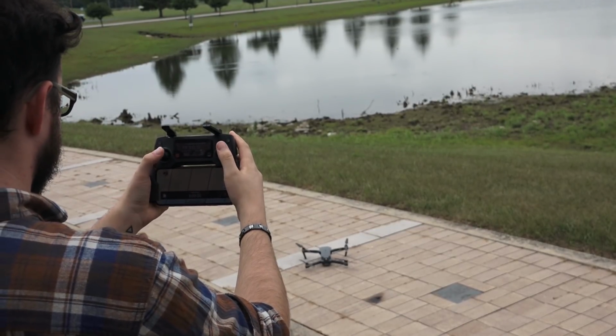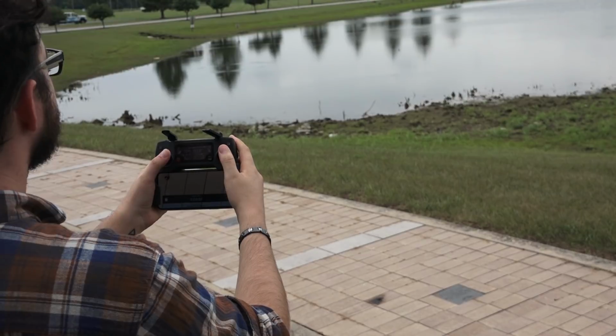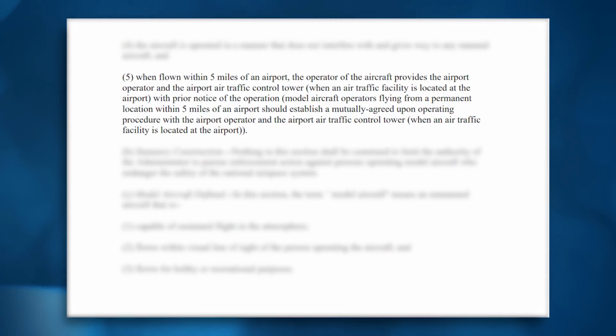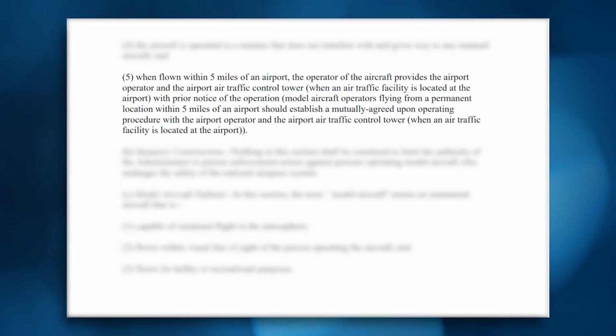Now, that request is then relayed through the FAA's network to the local air traffic control, which has the option to approve or deny it. The whole process has the potential to work in nearly real time, as do requests from manned aircraft. For airports not covered by UAS-FMs, pilots can still seek approval directly from the FAA. Recreational pilots under Section 336 are not required to follow LAANC at this time, but are still required to notify all airports within 5 miles of operations.